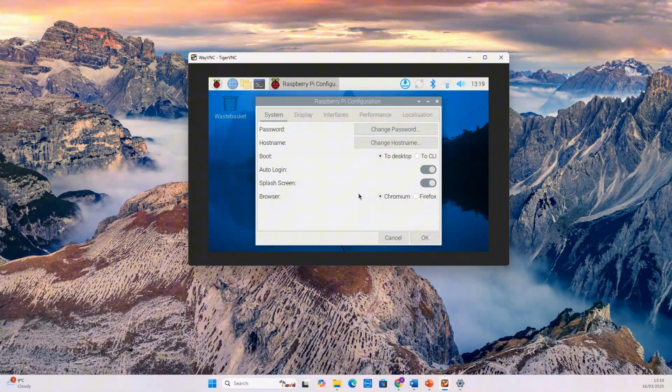So what we did before the Raspberry Pi installation, you can change here: your password and host name. You can also change the Wi-Fi options here. You can change how the display is going to look, and you can also enable or disable some of the interfaces. We'll discuss these things later. Here we enabled VNC and SSH. These two will help to remotely access your Raspberry Pi.